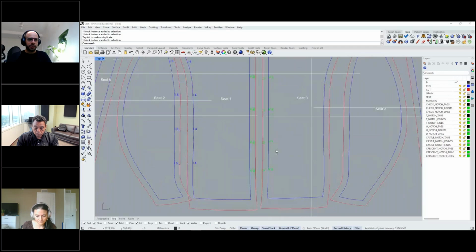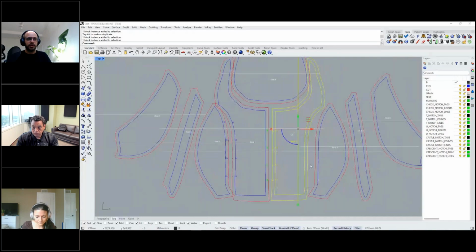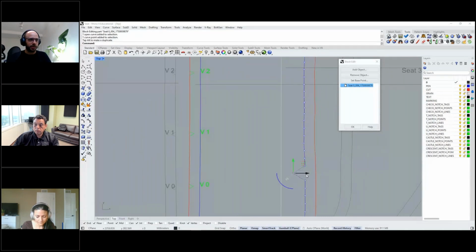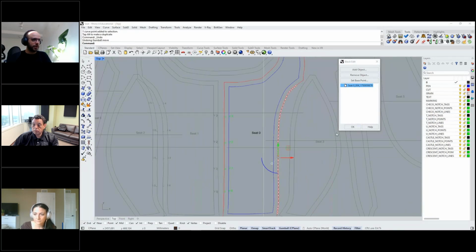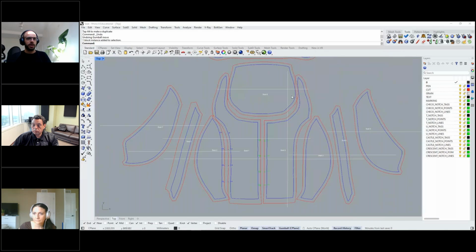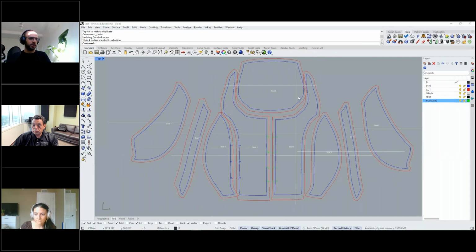If you need to edit this CAD block or the geometry for any kind of reason, this is just simply a vector file. So if you, for example, open this up with any 2D CAD viewer, in this case in Rhino, I can double click at the geometry and this will show me the boundaries, and everything is just simply a vector polyline because of the profile that I chose. We can see that we got all of our features there, and also we'll see a grain line for each one of the pieces, which will be horizontally oriented by default. So in this case, since I changed the grain line orientation, it is different, but for the other pieces, it will be horizontal, though we could just simply hide that grain line or disable it from export if we don't want it.